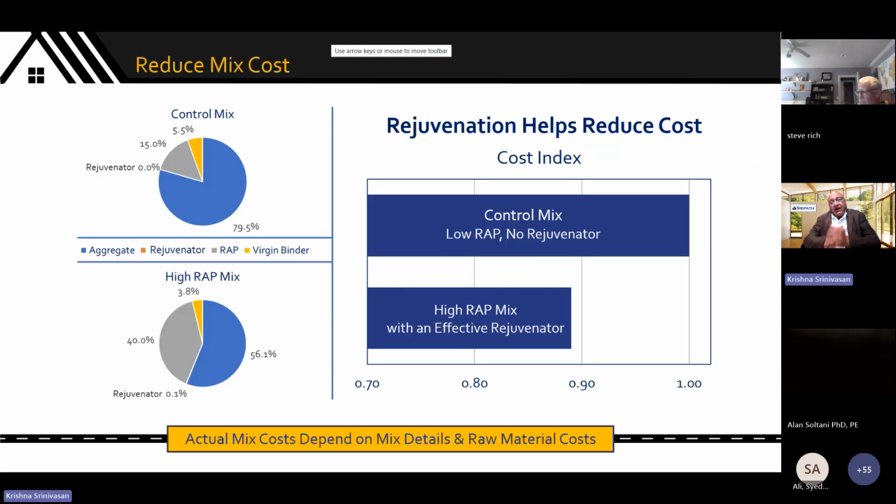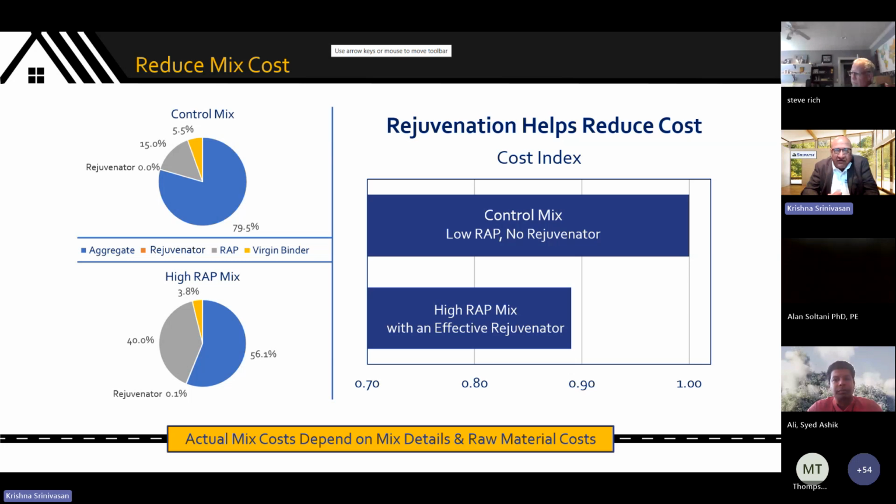So we've spoken about a lot of things. I want to highlight, certainly when you look at reclaimed asphalt pavement, the environmentalist looks at the sustainability aspect. Again, I didn't mention this, but one of the reasons why bio-based rejuvenators have caught fire in several different parts of the world is that, depending on their composition, they generally provide a net negative number for the GWP.